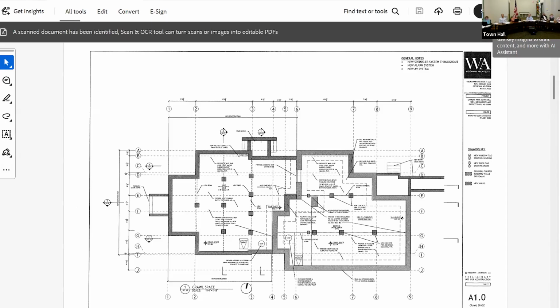One of the things that was brought to our attention was the shallowness of the foundations. So one of the things that's incorporated in this set of drawings that will be part of the cost estimate is digging out underneath this portion so that there's more headroom, and sealing it from the inside, and then sealing up all of the vents that are around the outside of this building, which are right below grade. It's caused a lot of moisture to come through, and there's humid air under there, and there isn't a good vapor barrier. That work is in addition to reinforcing the supports of the primary members that are under here. So that's the historic portion. And then we're going to have a depth of about 3 feet.